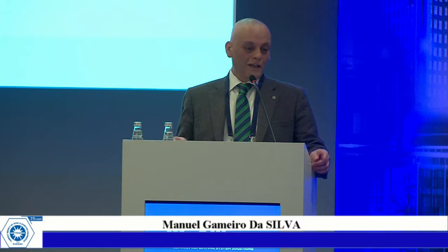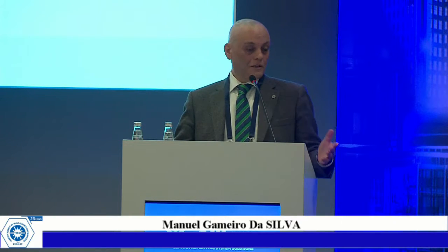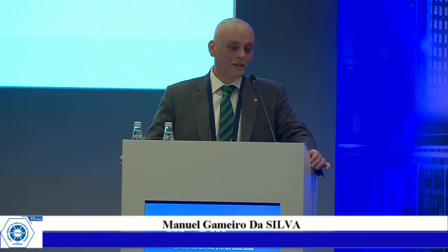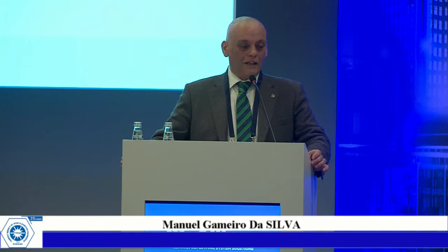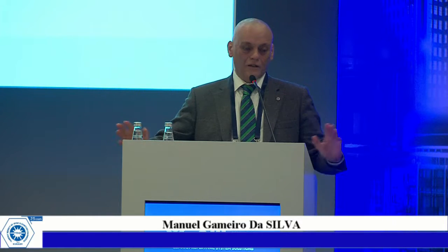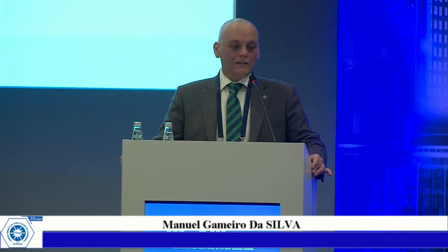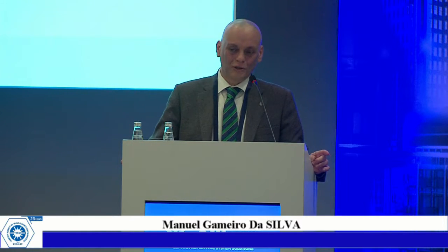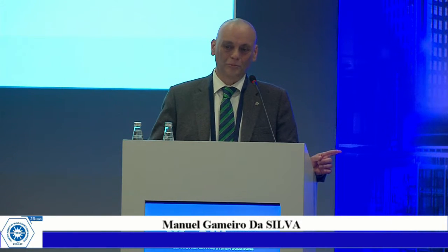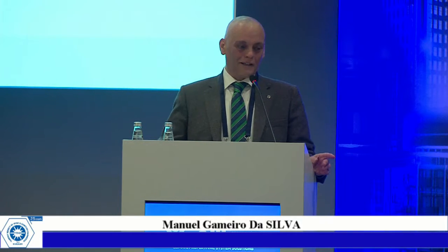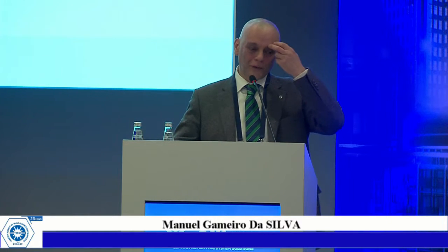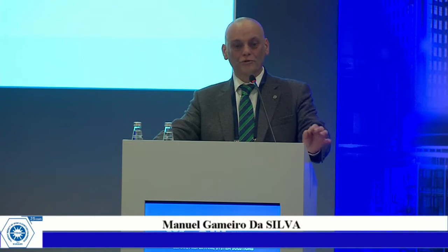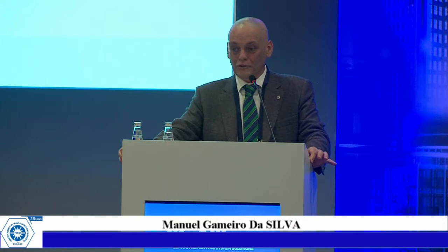And we also show in this graph here the breakdown of the thermal fluxes of the human body. And for instance, as you see, this was a measurement in my home, in a normal situation. And as you see, the losses by radiation are the most important. So in case we want to have a good control of the environment, we should measure the mean radiant temperature.